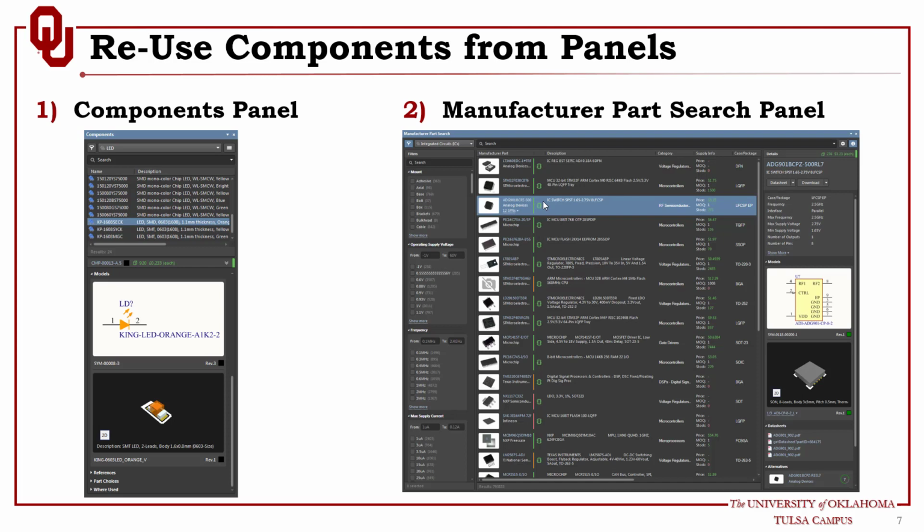Usually the life cycle state for a component starts with draft. If you are creating a component, the first stage will be draft. Then once you are done creating the component, you transfer it from draft either into prototype, meaning you are using this component in prototype before you test it, or you transfer it into production, which is green. Once this component is no longer in production, or it's not recommended for new design, you transfer it into not recommended for new design, which is the orange one.